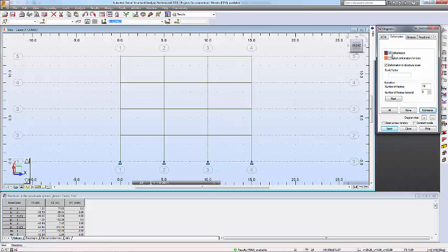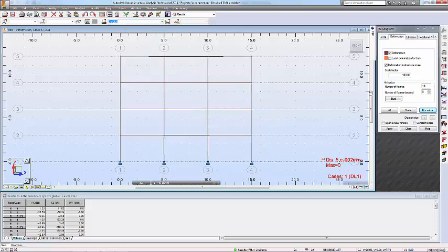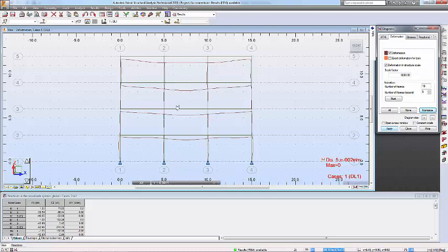So first we have a look at the deformation. This is the deformation for combined loading, and if you are interested in what the dead load is, this is the dead load deformation. They're pretty small, so if you want a quick, clear view of it, we can change this to 5000. That gives you the view of the vertical settlements due to the vertical loading.